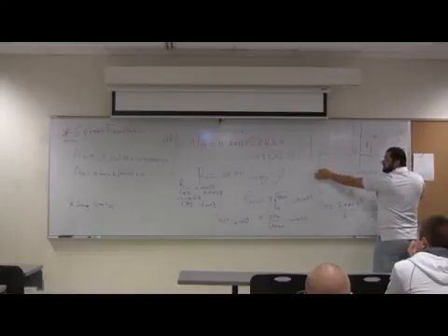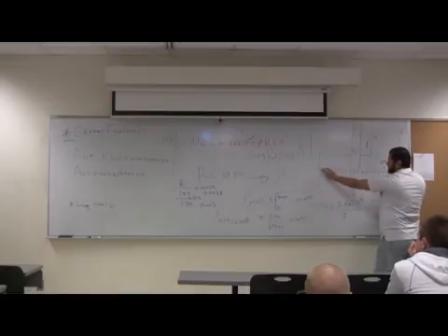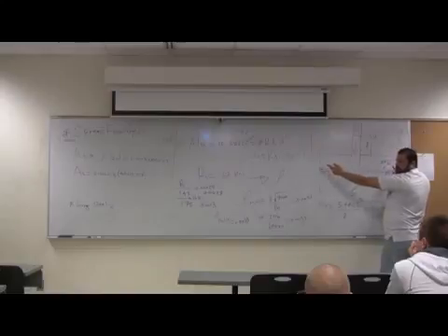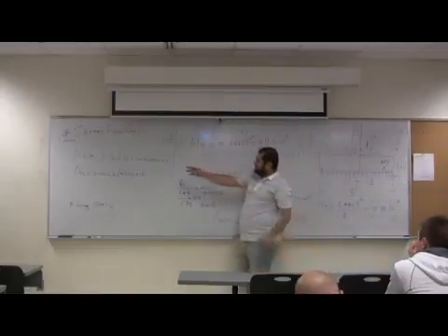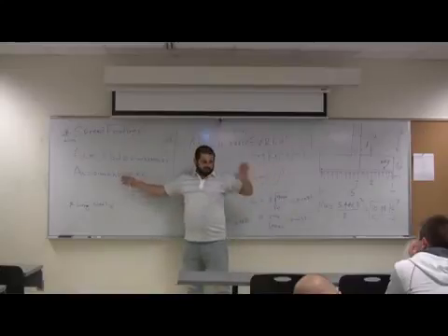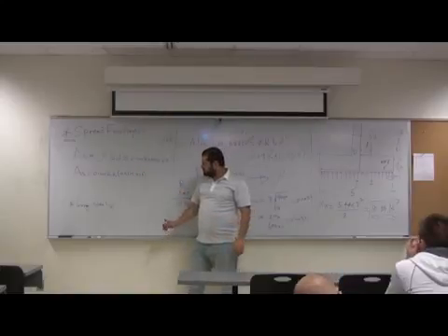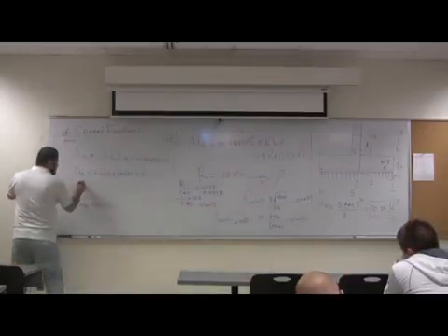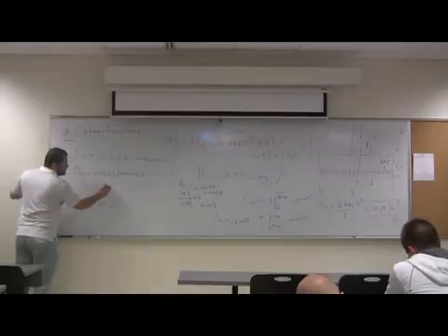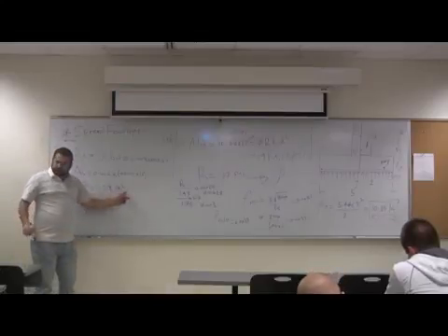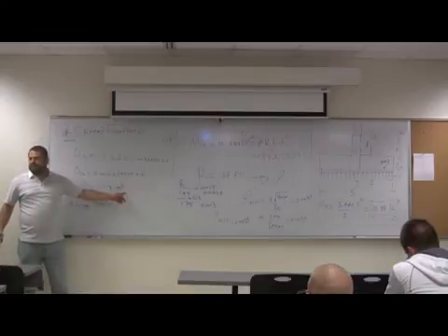So I took the cover 3 inch and 3 inch. That's 6 inch, half foot, and I already have 5 in here. So this will be over a width of 4.5, so that's 4.5 times 12. That's B for this one, where the longitudinal steel will be provided. Times 12, that's H, because it's BH. How much is this? 1.3 inch square. Is this per foot? No, that's all you need.